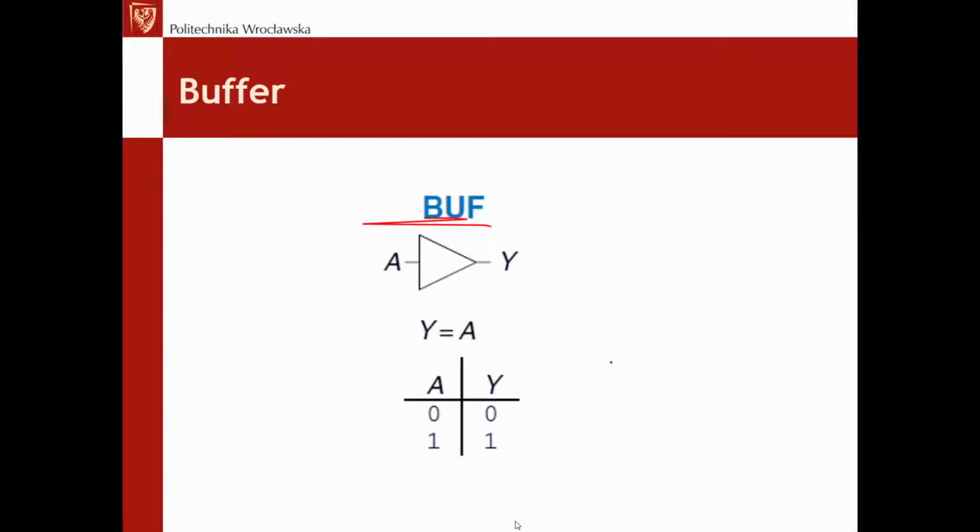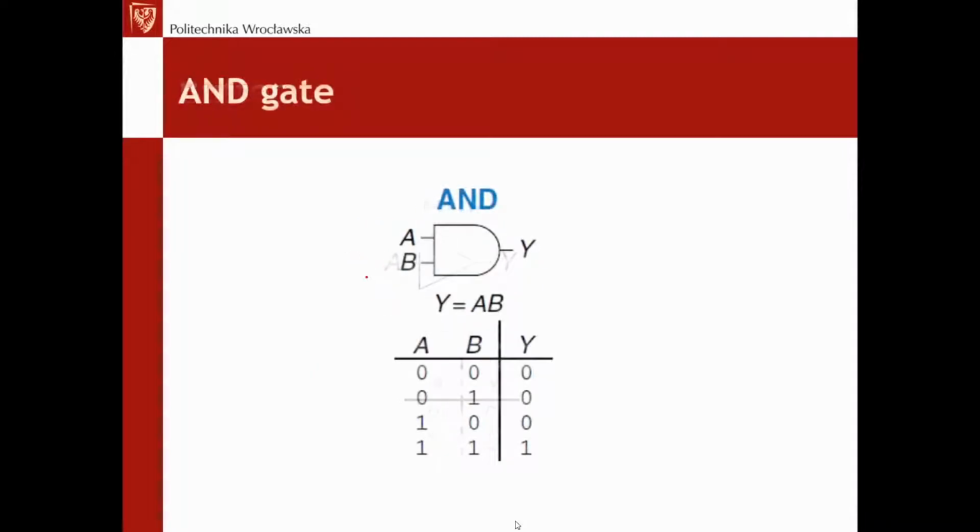the buffer is physically used for translating impedances, because that's the reason why we are using buffers. We have high impedance here and low impedance there. That's why the buffer is used. In other words, it's strengthening the signal, or isolating two parts of the circuitry. That's why we sometimes use buffers even in logic circuitry. Buffers in logic are also quite often used to translate signal levels, but about it slightly later.